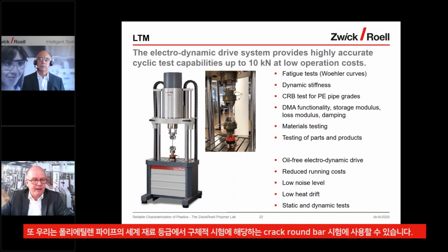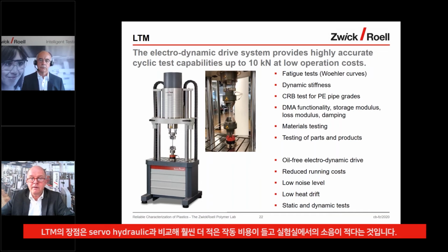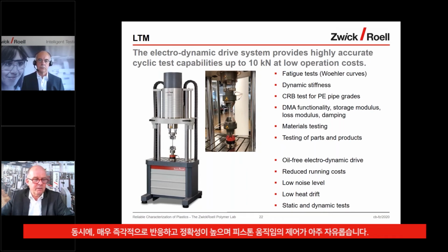The big advantage of such a machine compared to servo-hydraulic is that it has a much lower running cost. It makes much less noise in the lab. And one big advantage is it is completely free of oil and oil fumes and so on, which is a typical problem with servo-hydraulic systems.